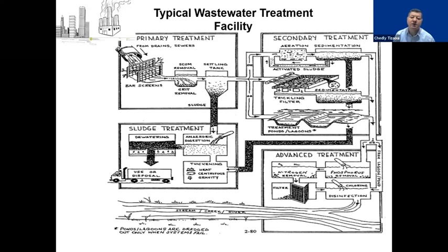They involve using microbiological species to remove the dissolved fraction of the organic matter that is problematic in the wastewater. And they could also remove part of the suspended particles that are still in the wastewater. That's the heart of it. That's the main purpose of biological treatment.